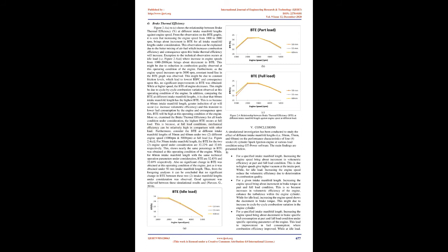More so, examine the brake thermal efficiency for all load conditions under consideration. The highest BTE occurs at full load. This is because, at full load conditions, mechanical efficiency can be relatively high in comparison with other loads.